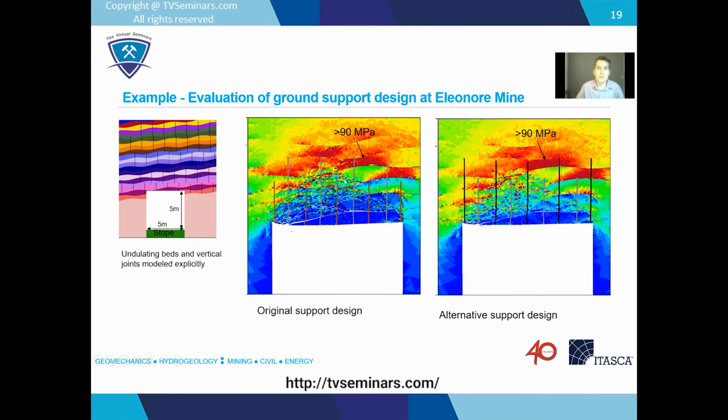And you can see in this middle plot here, these black lines are representing the cracks between these tetrahedral blocks. And then you can see these more large scale openings along these bedding planes and so on. So being able to include this discontinuous behavior in the continuum model was definitely important in this case.